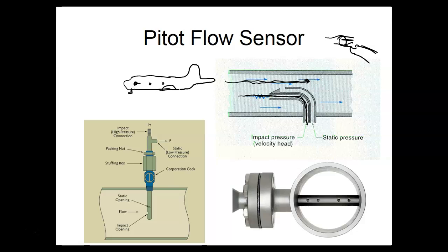And that's what was nice about this on an airplane, is that no matter how high you was flying, you could be flying at 35,000 feet, and your pitot static system still worked, because the pitot pressure would go down, the static pressure would go down, and the differential would still be the speed.